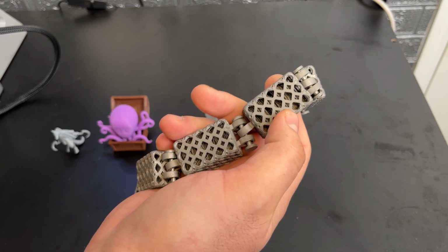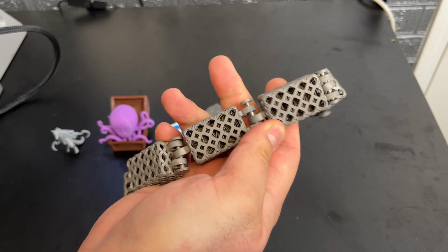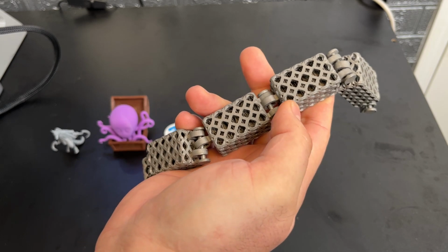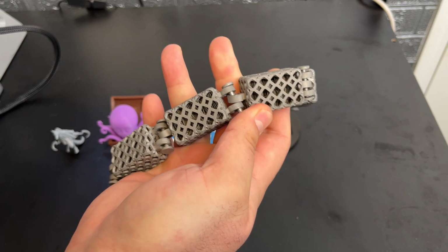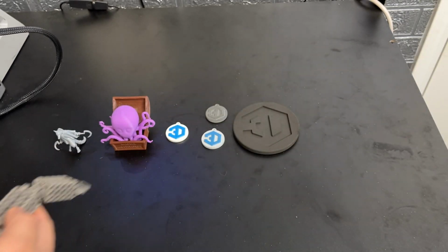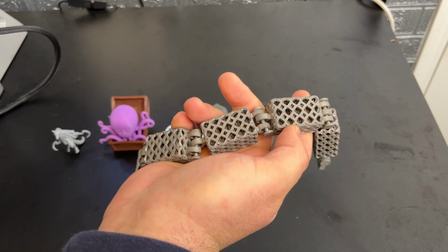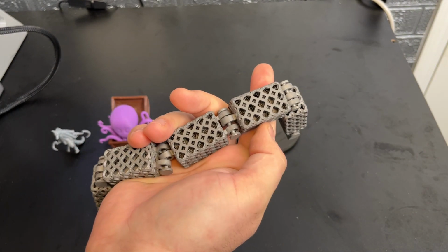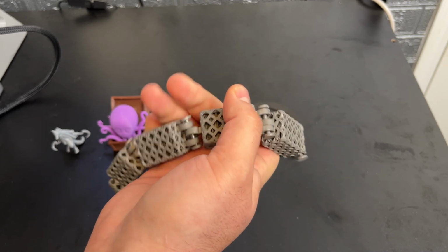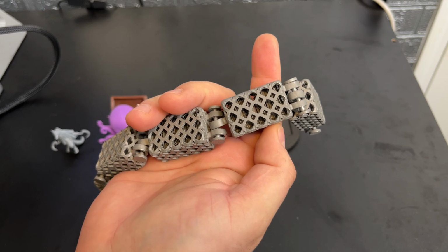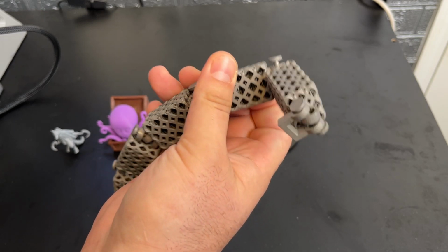super amazing. They create structures that are kind of hollowed out like this so that bone structures can integrate with them. So medical implants are really strong in this area. This is the highest strength on our strength hierarchy over here. It's very high strength and produces dense and strong metallic parts. The materials that can be used are metals like titanium, stainless steel, and aluminum. And the one that JLC 3DP offers is stainless steel, like you see here.